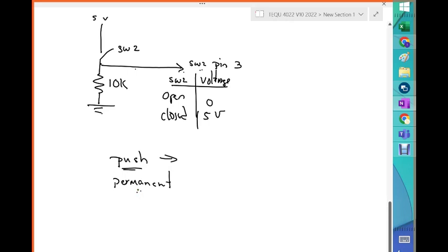So what we're going to use is a permanent switch, meaning that I will activate the switch and it will stay there. If I want to deactivate the switch, I move it again and it will deactivate. Push buttons are bad in the sense that they will not work for our level sensors. Our level sensors, when they engage, will stay there unless the condition disappears. A push button requires you to keep your finger on it to maintain it engaged.